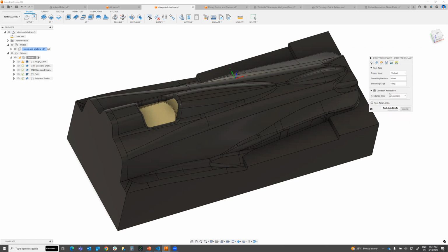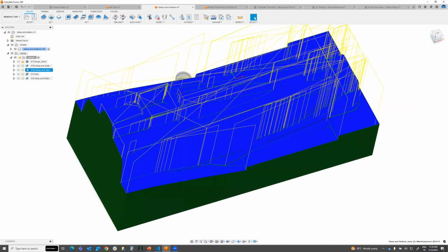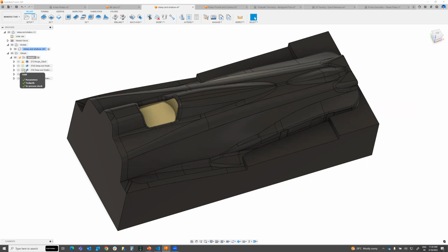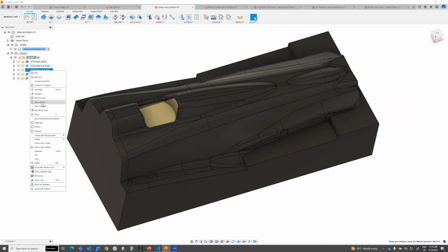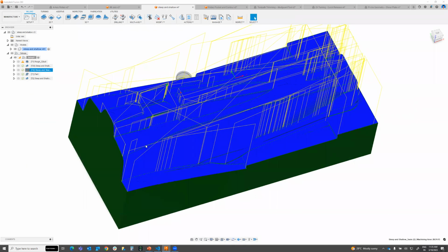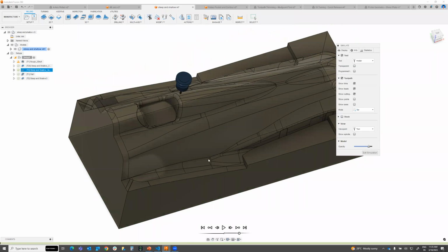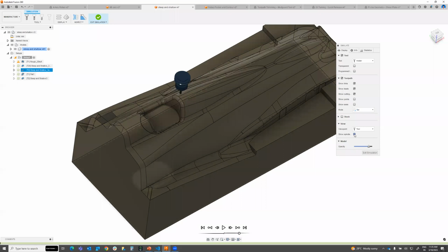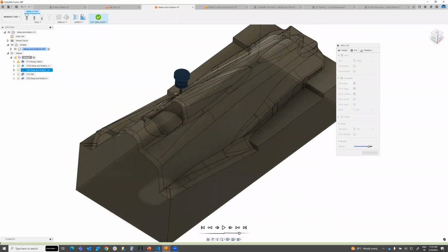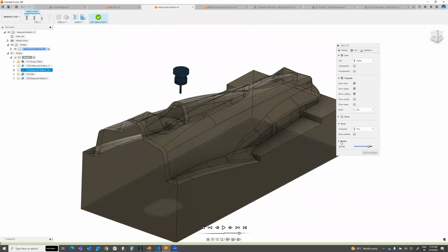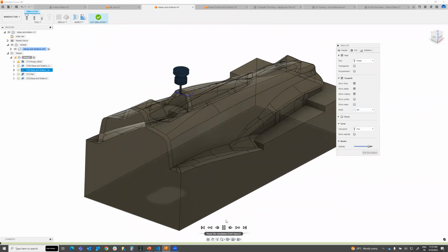Now I have changed it to automated and the tool axis to vertical. Once you are done and the tool path is calculated here, you may want to see the simulation on that particular tool path. Suppose I look at this particular point, you want to see how the tool is tilting, and you can observe. I will just run the simulation.